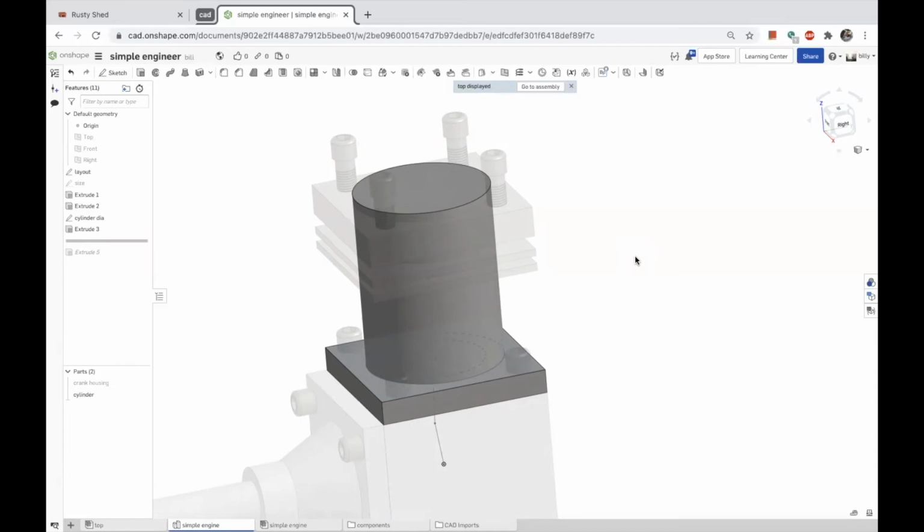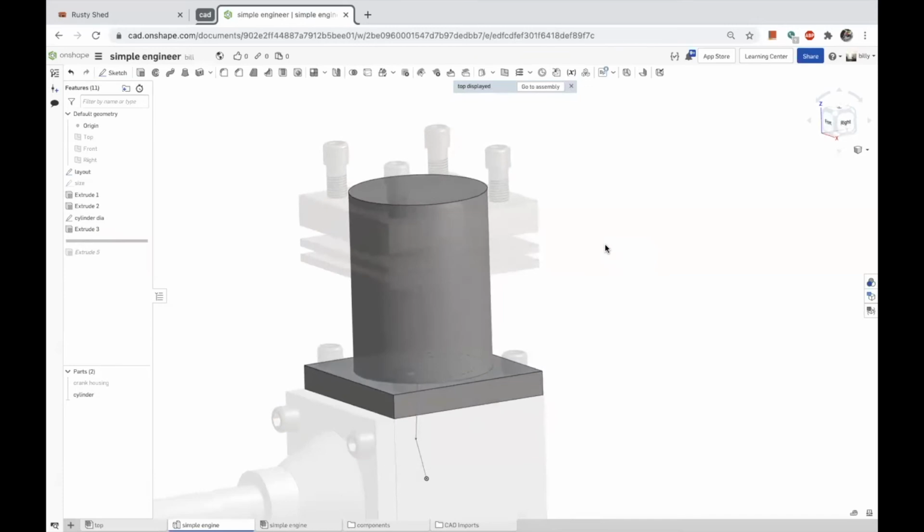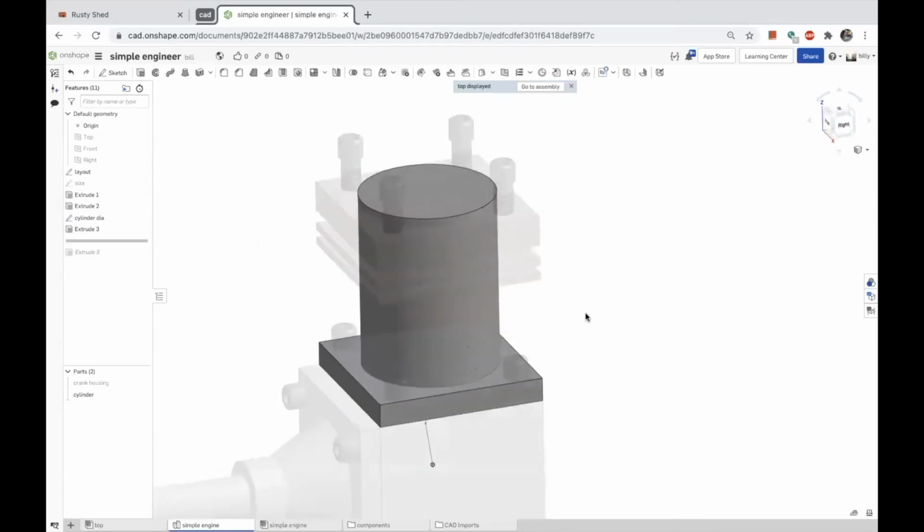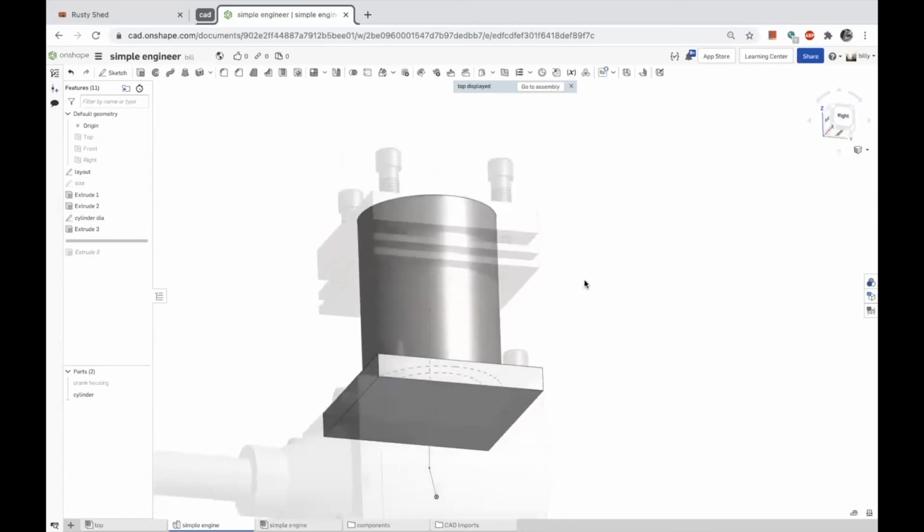What's a fast way to do this? I want this shape to go down, and then I want this thickness. So what I need to do is move this reference surface up to this distance and then add thickness to it. So let's try that. It's kind of funky, but let's just get this thing rocking and rolling.